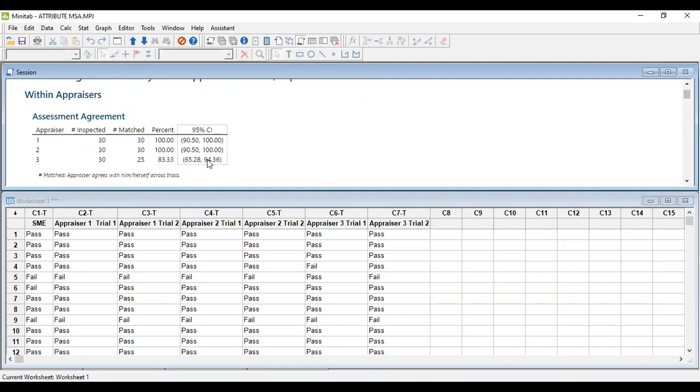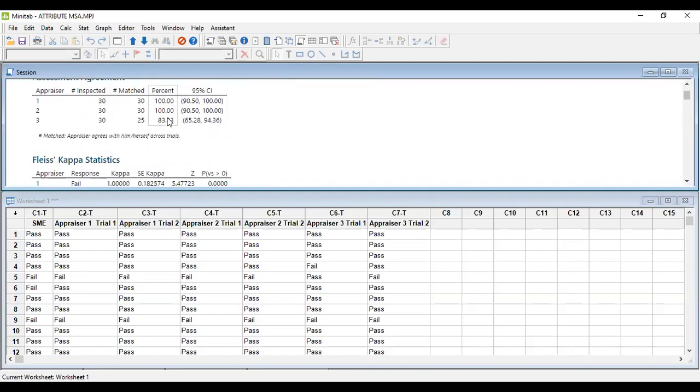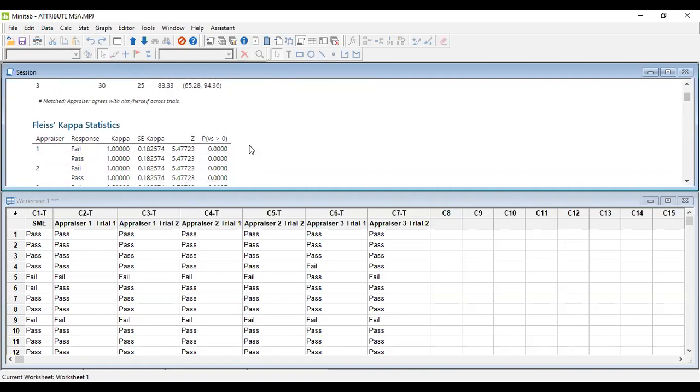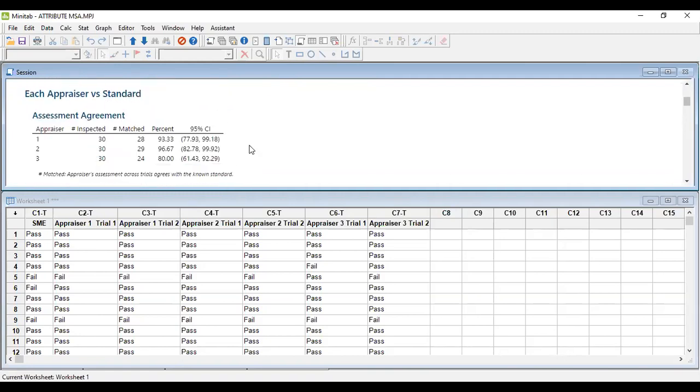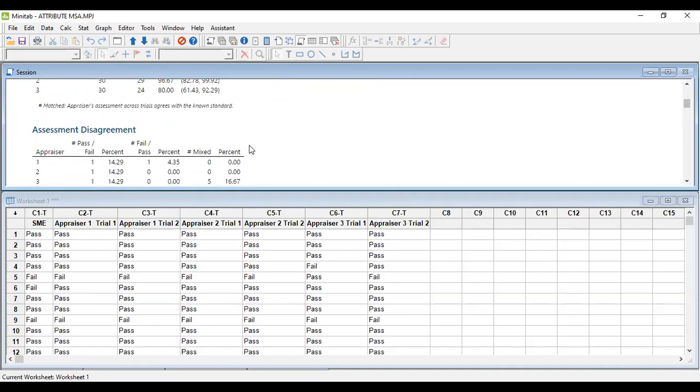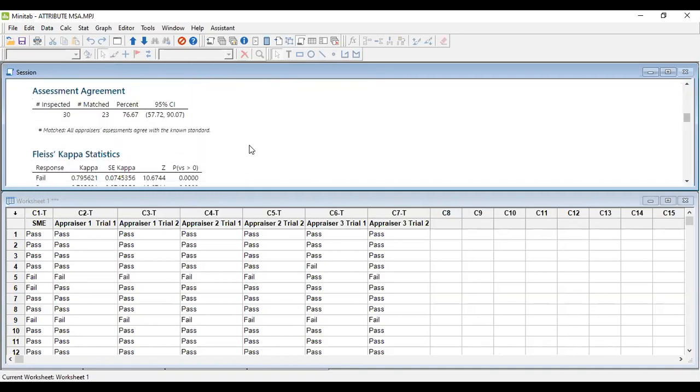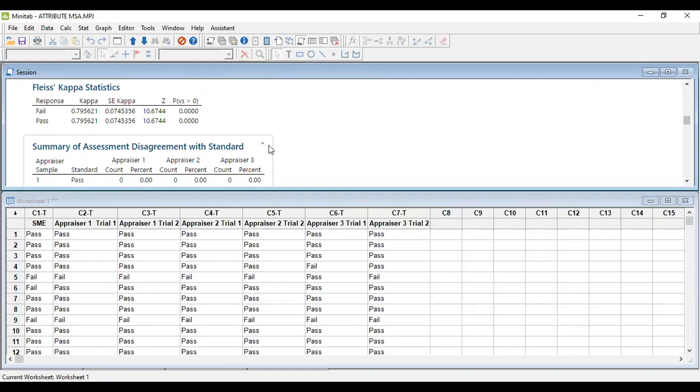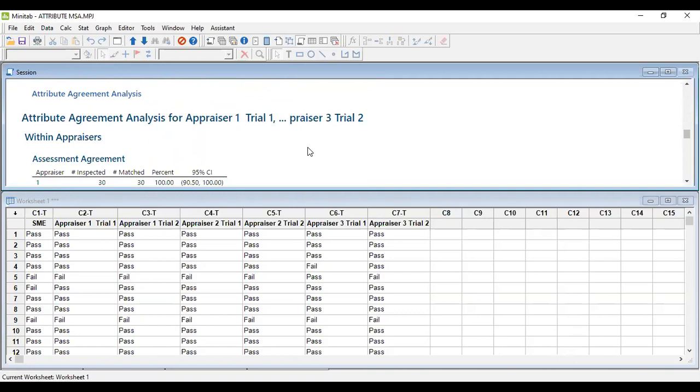What is the total? So we will get to know which appraiser has an issue, or if there is any repeatability issue with the gauge, or if there's any accuracy issue that we are facing against the standard measurement that has come through. And based on this, we will be able to fix if there's a problem with the measurement system. Clear? Sure. Okay.